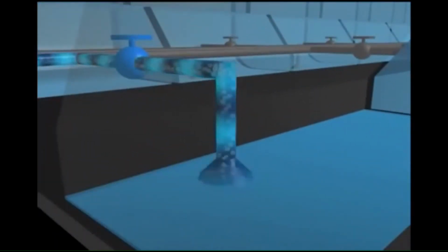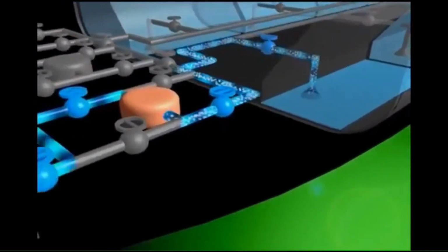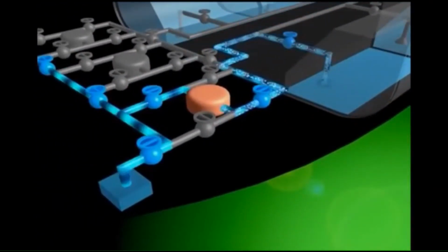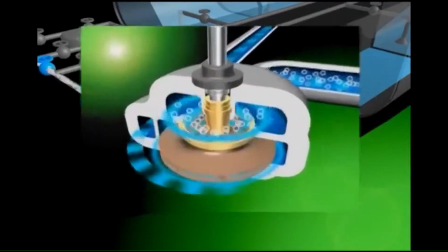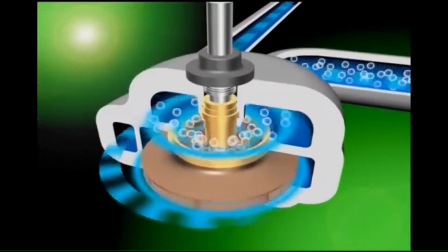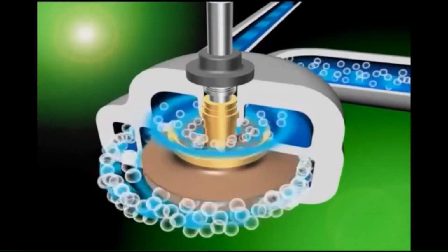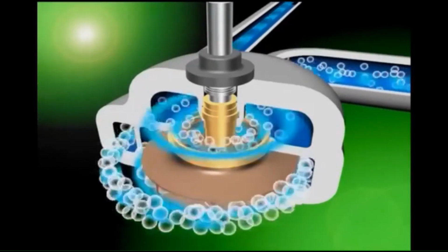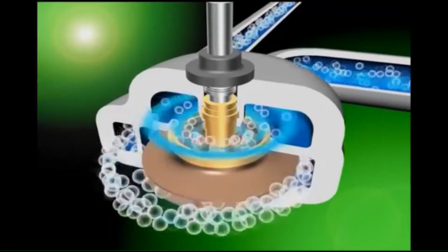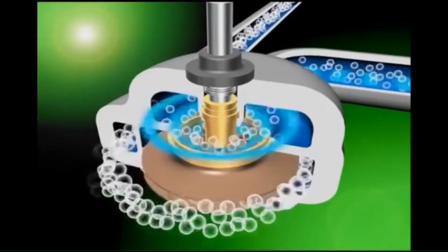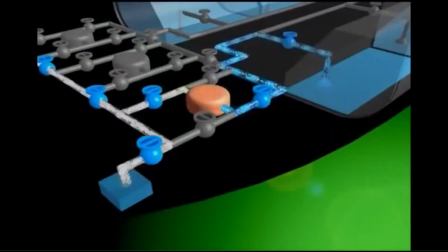If a pump draws in air while in operation, a noise is produced, and the amount of seawater discharged decreases, significantly lowering the pump's operating efficiency. Also, the amount of seawater being discharged will drop to zero in an instant once the pump has drawn in a large amount of air. Why? When a small amount of air is drawn into the pump, the air passes out of the pump together with the seawater. But if a large amount of air has entered the pump, it gathers and gradually spreads to the pump periphery, decreasing the centrifugal force the seawater receives from the impeller and disabling the pump from discharging.